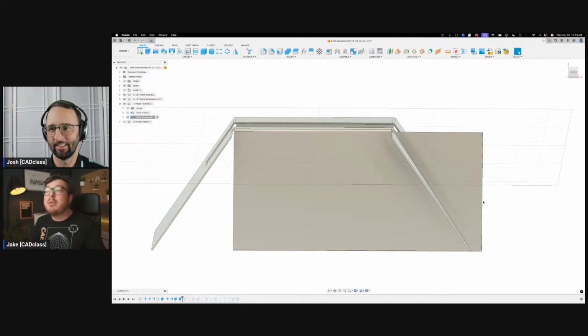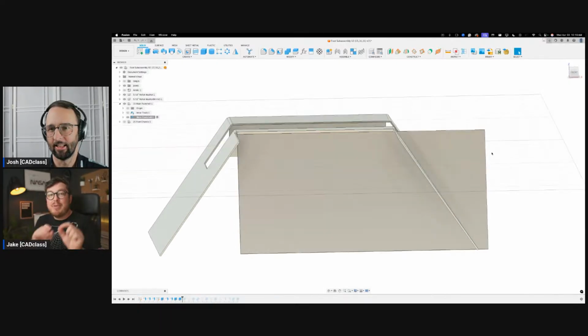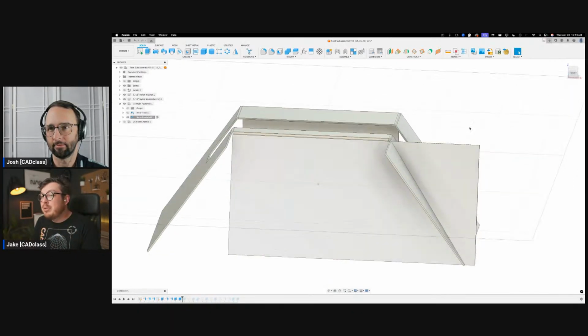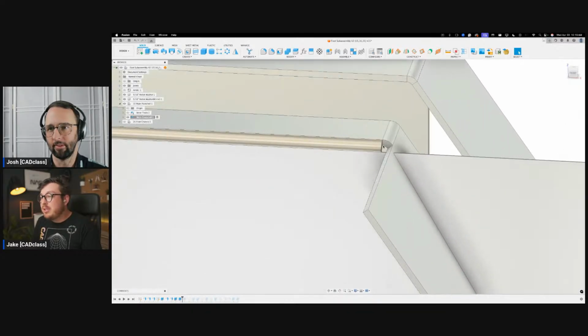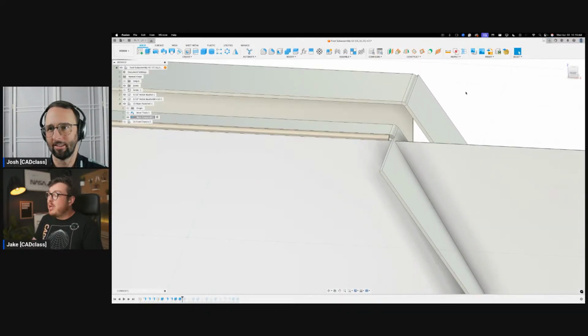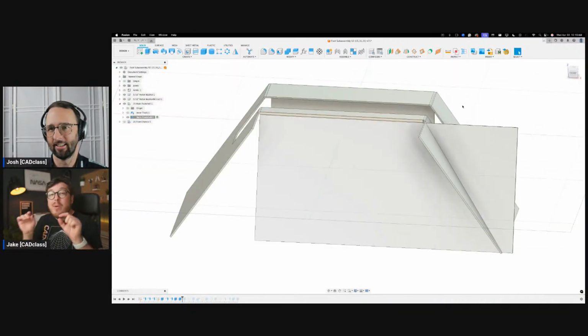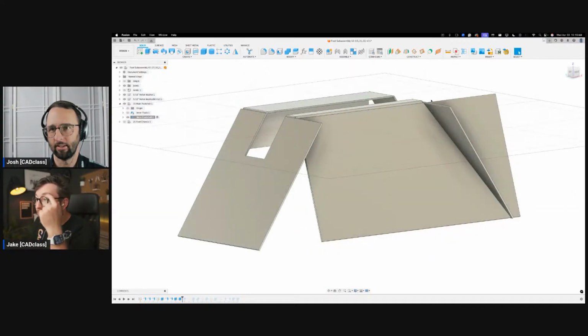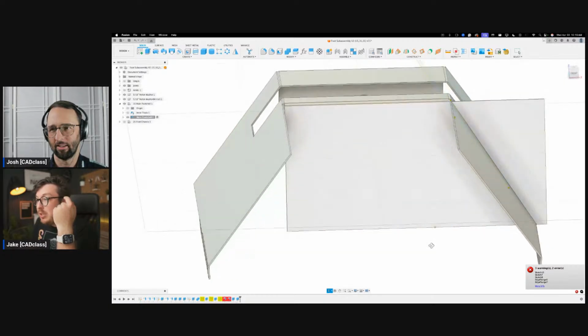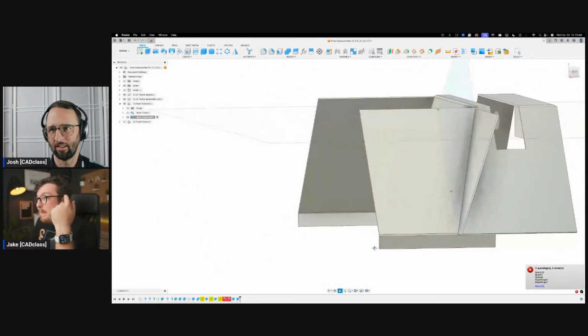Anytime you're designing sheet metal parts, they physically need to have a small separation, a small gap in between. So you'll see on corners, there's a certain area that's missing. That's totally fine. I'm going to be going back and TIG welding all of these aluminum parts. That's not a problem. I want to have built-in gaps. I want them to be as tight as possible, but that's fine. But straight up, enclosing all of these is absolutely maddening.